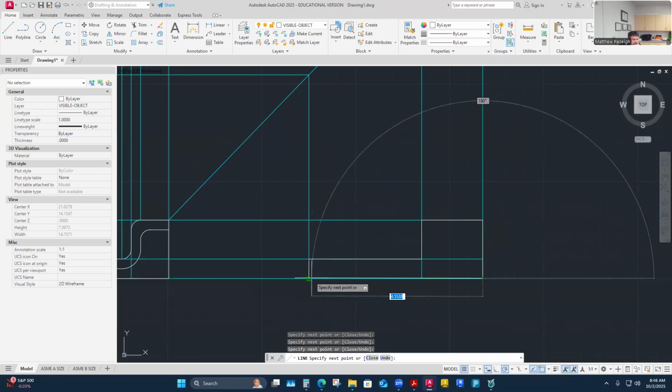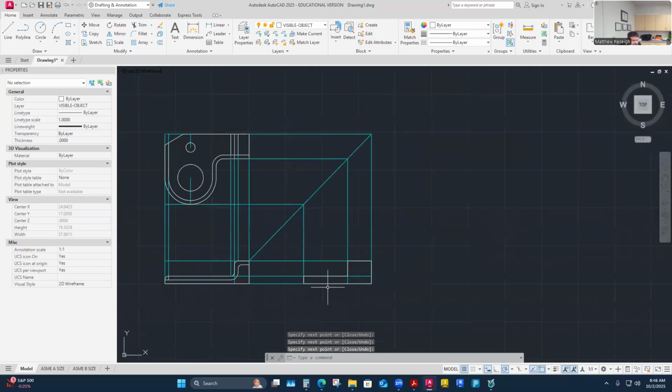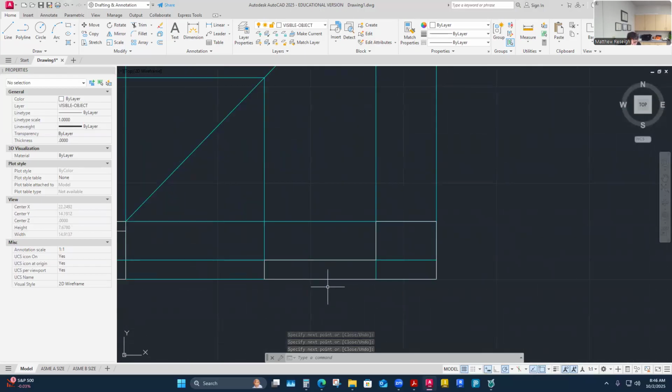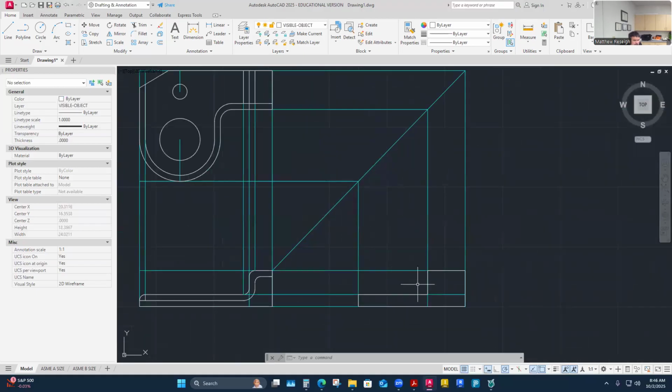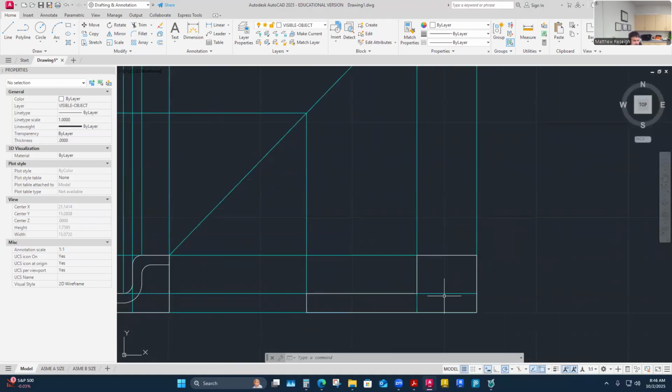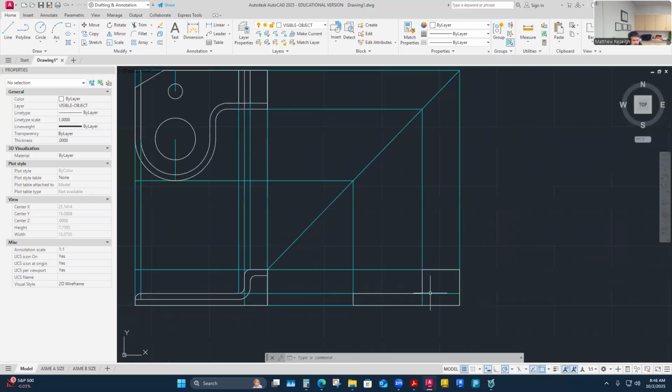If you overlap construction lines, that's a good scenario. If you overlap visible lines, not great. Machine cutting doesn't like that. Not that I would do that here, but even having extra data in there that you'd be sending as a model to a 3D printer or something, you would want to kill those layers, which we can do. It's not the end of the world, but if I can prevent it, I will.